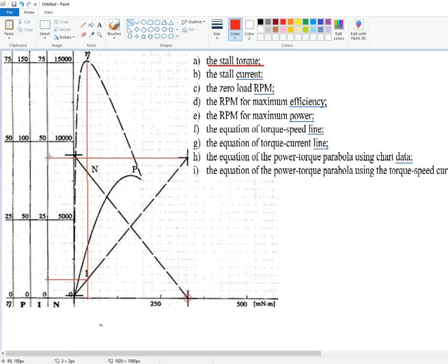Or if they do attempt to, as you stall the electric motor, the voltage will drop. Everybody knows when you crank the engine with the lights on at night in your car, the lights dim because the battery voltage drops as the starter motor drags a lot of current.